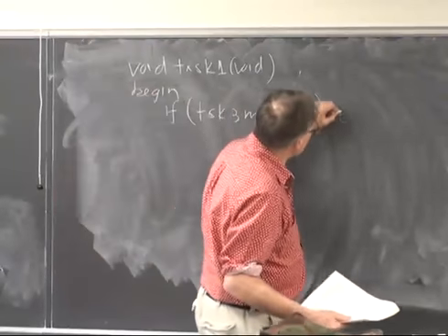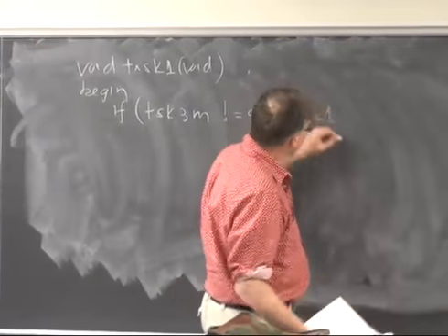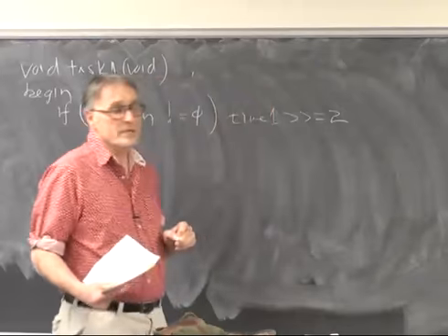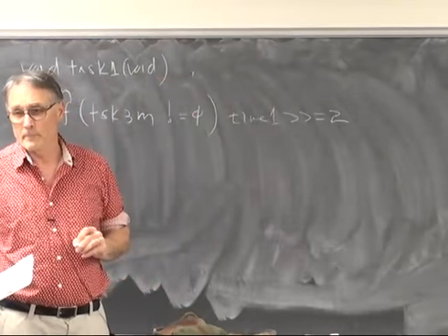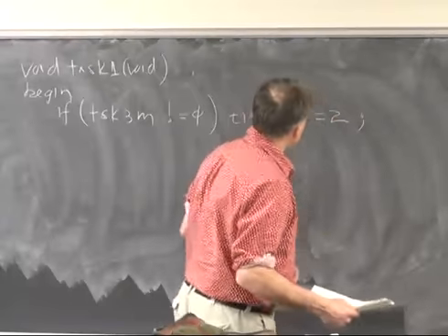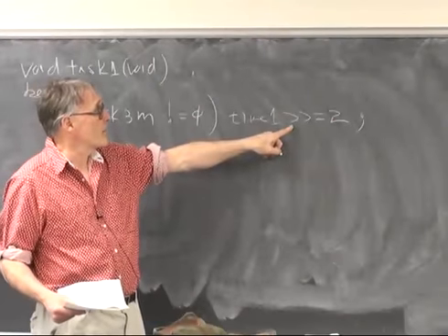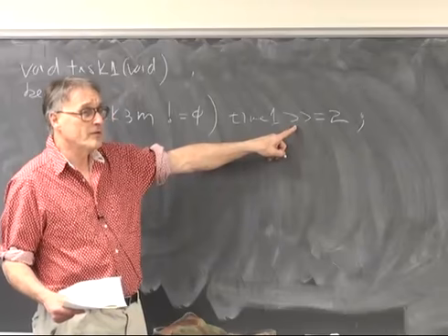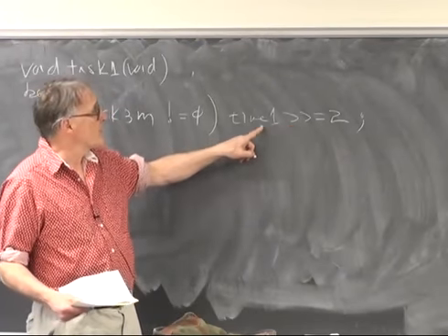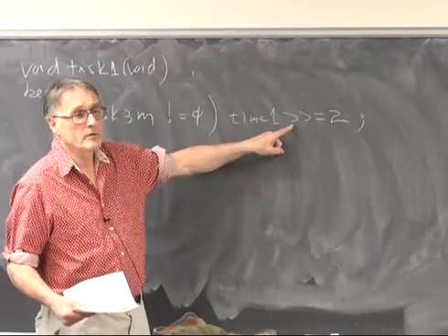And if it is, we're just going to speed up the blinking by causing this routine to reschedule itself earlier. So that's the weird C notation, as you probably know, for a shift by 2 bits. That's a divide by 4. And so the reschedule time has been dropped by a factor of 4, and so we go from 2 hertz to 8 hertz.